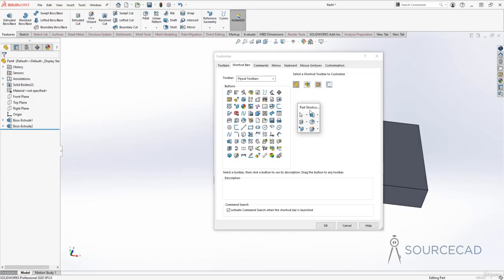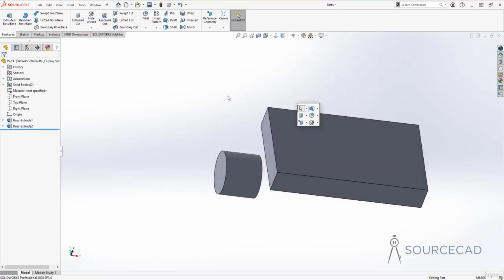So for that, you don't need to go to sketch environment. You just need to click on this sketch and this will show you the sketch shortcut panel. So from here, I'll just select the point tool, which we added in the example just a couple of minutes before. So I'll drag it and drop it out. So again, we are left with the default tools and I'll click OK. And that's the shortcut key. And this is how you can start making simple things in SolidWorks.